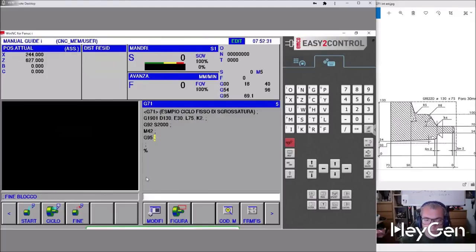When I set machine zeros, only done in reality, we need to know the tool radius. I'm using a radius of 0.8, already set. It's already empty, only this radius of 0.8, a virtual point. This indicates the machine to use G42, meaning we're doing the outside using a rhombic insert. Let's see if I can, yes, T0101 EOB.